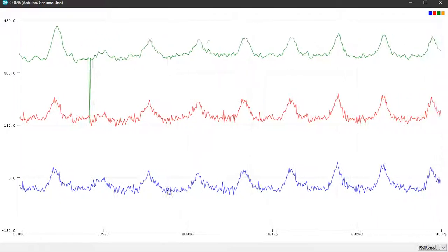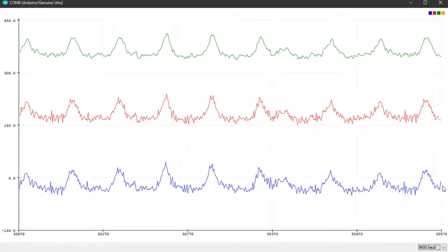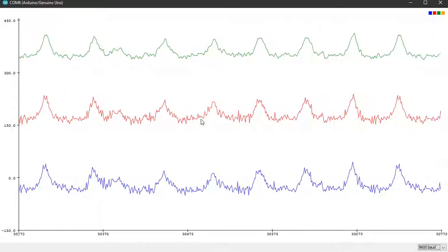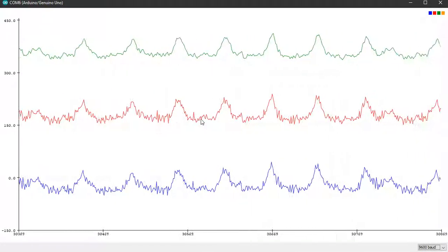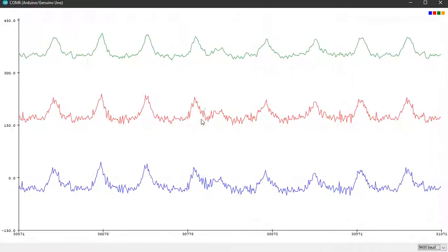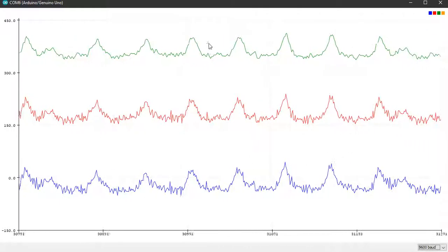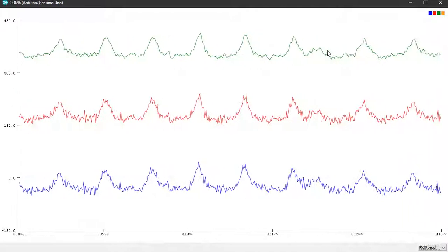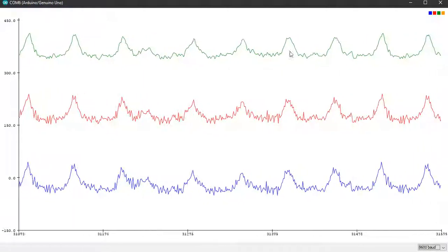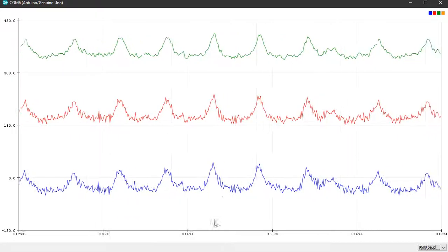The blue colored signal is the original PPG signal, which you can see is quite corrupted with noise, while the red colored one is the one after removing the baseline with the filter. In my case, the baseline wander is very slow, or it's really not directly visible, so not much effect is seen. While the above one is the output of your LPF, which is a slightly smoothened version of your input. Basically it has removed the high frequency noise. We still need to remove further noise so that we can obtain a smoother waveform.